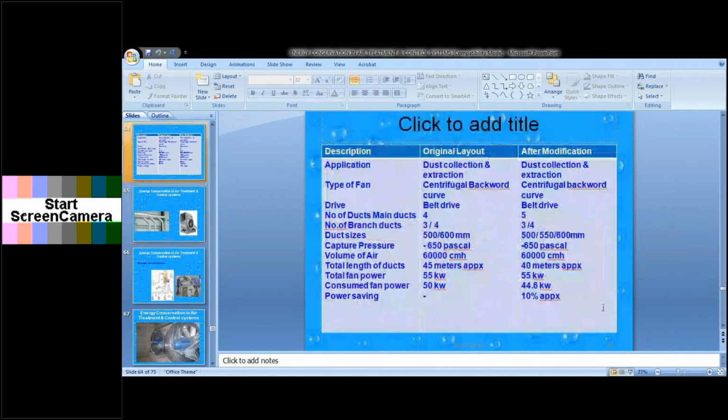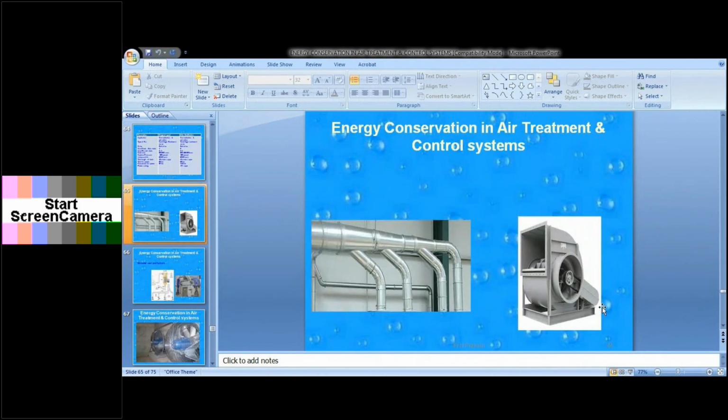Yeah, dynamic pressure as well as static pressure, because static is based on your duct sizes. For a particular velocity, if you have high velocity it means there will be more pressure drop. Low velocity means less pressure drop. For a particular air quantity and pressure, we have to see in the duct charts. Round size duct charts are there. There will be pressure drop in one column, and the other column will be volume.